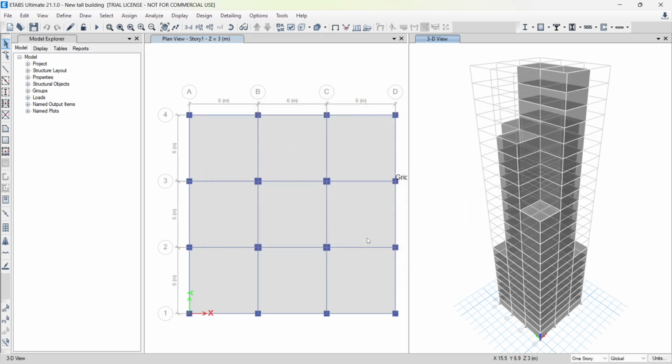We will now set the load case by including the response spectrum function we have just defined. We need to enter the acceleration values to define the load case for the response spectrum function. So check the units of acceleration parameter before proceeding as we did earlier.